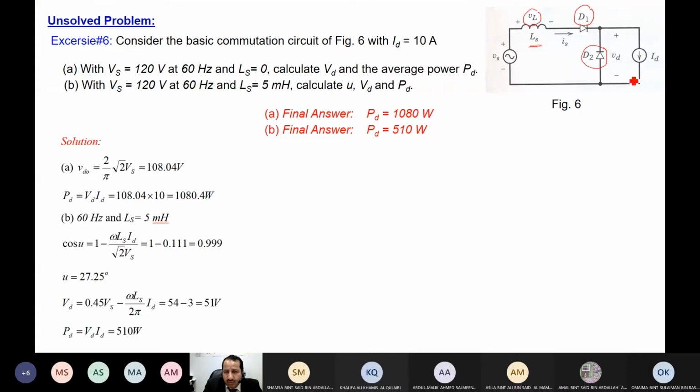And when it is released, you remember what we say? We say the diode would be forced to keep conducting the current in the opposite direction, which is not desirable because it is designed to conduct in one direction. So to avoid this conflict, we connect diodes similar to this in parallel with the load. So there is a way to circulate the energy, rotate it, and then consume it.